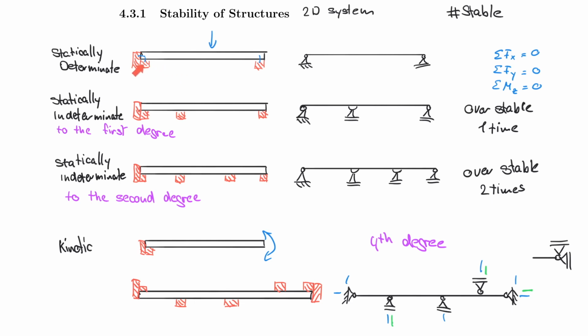Why were you able to solve support reactions for systems like these? You have done this already in your homework, but why would you not be able to solve these systems? And the answer is actually on this page here right now. And of course, I'm not telling you too much if I say that this is the real reason here. The reason you can solve these simply supported beams so far, and not these systems below, is because you have 3 equations, or 3 conditions. And when you want to solve 3 equations, you can solve to a maximum for 3 unknowns.